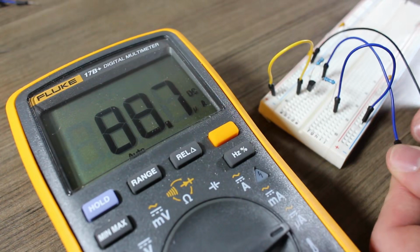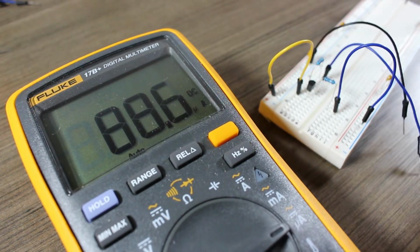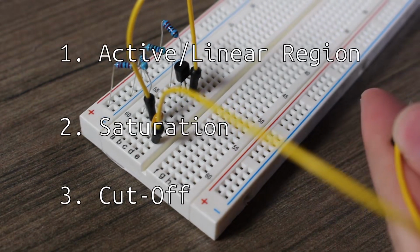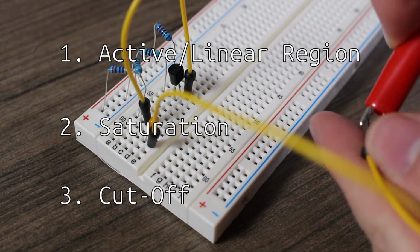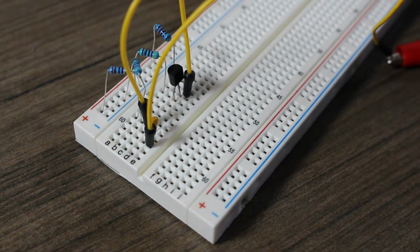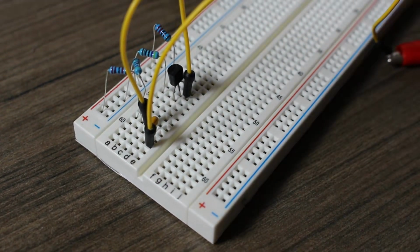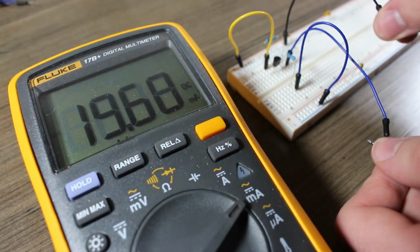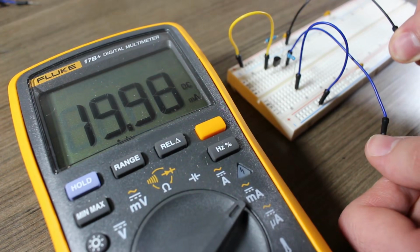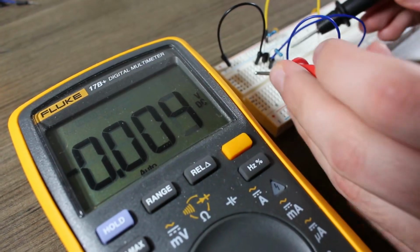To explain this phenomenon, let's take a look at the operating modes of BJTs. BJTs have three useful regions of operation: the active or linear region, saturation, and cutoff. Cutoff is easy to explain, since it simply means that the transistor is just off. The active region is what the previous experiment just displayed. The transistor will drop whatever voltage is necessary in order to keep the constant current.